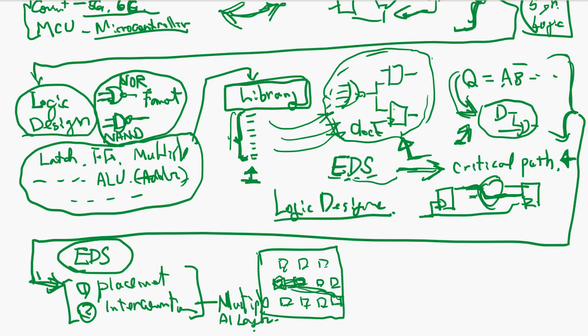So once this is created, if the software causes an error, then maybe you have to work on the error, because maybe it ran out of silicon real space. Then you have to increase the silicon chip size.